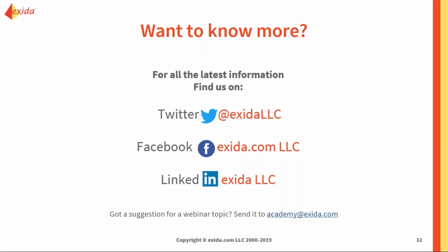So you should definitely look at your safe failure rate for each device to calculate that spurious trip rate. However, the hardware fault tolerance is going to be independent of your spurious trip rate. It could influence it, but it's kind of two different topics. But if you're adding redundancy, there's a very good chance you're adding to that spurious trip rate.